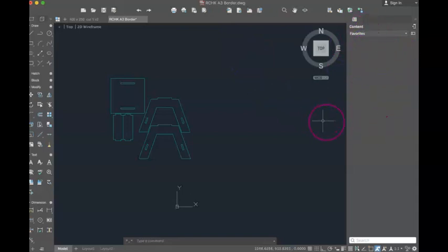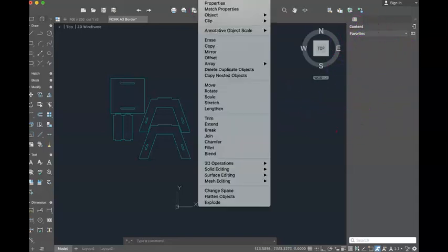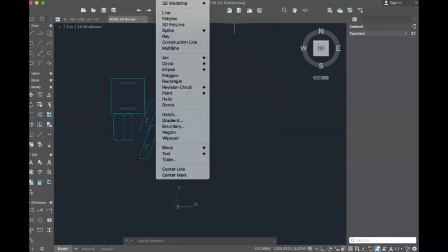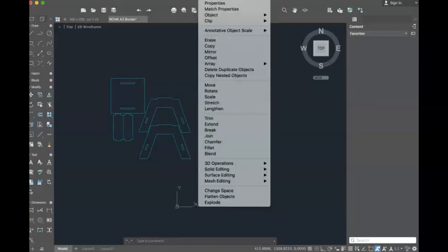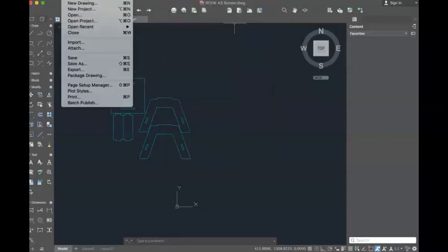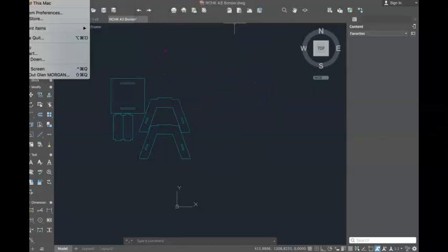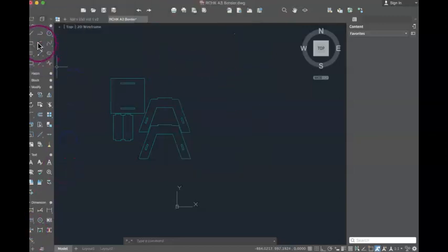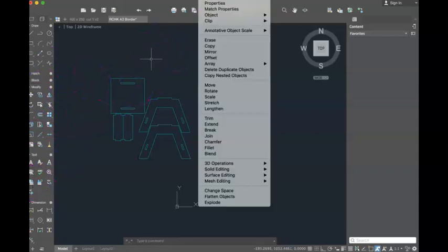Now this is all in millimeters because I've set that up for you, but you'll notice I've deleted some of the borders and things. All the pull-down menus come from up the top here: Modify, Dimension, Draw. These are the three main ones that you will use, as well as File. Those are all repeated over the side here: line, circle, mirror, extend and trim, offset, all of these commands. Here's the Modify toolbar down here, and here's the Modify toolbar here. So they're all repeated as symbols.